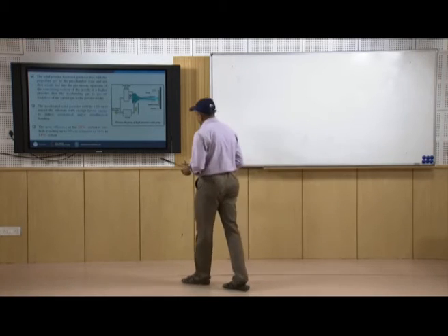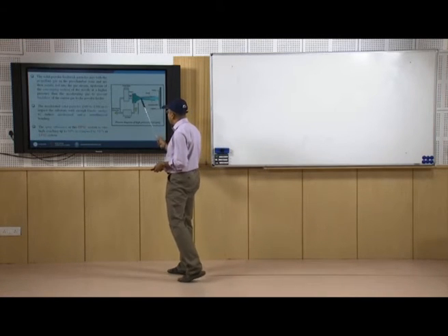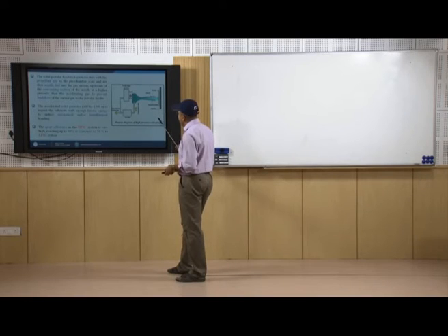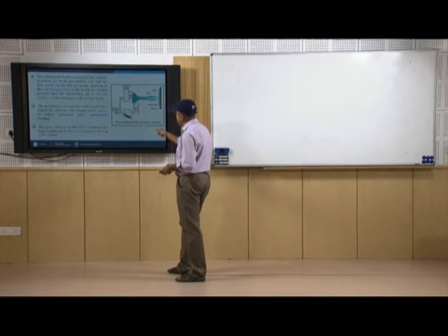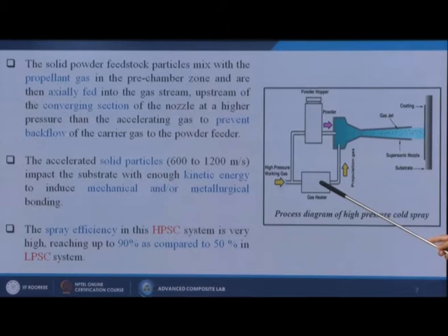So in this particular case, this is the process diagram for the high pressure cold spray, where we are applying the high pressure working gas over here. We have the heating arrangement over there with which we are heating that gas up to 1000 degrees centigrade, then the gas comes into this chamber, we put the coating powder into this chamber, then powder and gas mix in these sections.